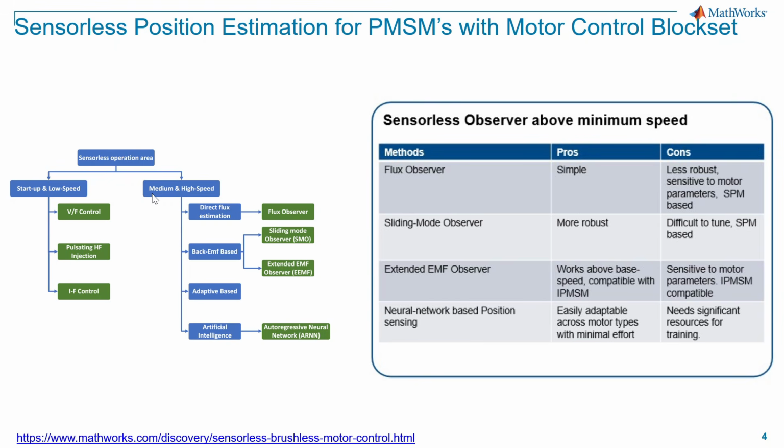However, when the motor is starting up, we have nearly zero back EMF, and that is where we need some kind of a startup technique to move forward with these sensorless techniques. And there are different options available with Motor Control Blockset for these as well. So overall, to support your sensorless implementation, Motor Control Blockset offers pre-built blocks and reference examples which showcase how these blocks can be integrated, thus helping you jumpstart your implementation. So in this video, we will focus on the AI-driven approach using a neural network, showcasing how data-driven models can be used